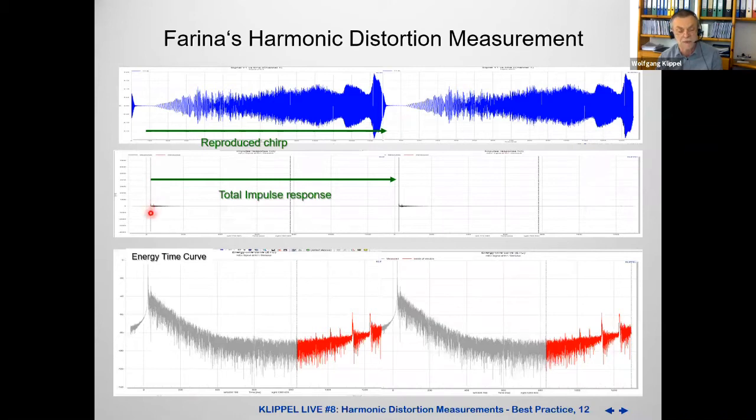We are taking the absolute value and taking the logarithmic value from that, so we can look down almost 80 dB. Yeah, that's a lot. And what you see here is more or less the energy from the impulse. It's close to 0. Here is the same information. And then we have the decay from the room reflections, then comes noise. And then you see again some peaks in that. And those are the acausal responses from our nonlinearities.